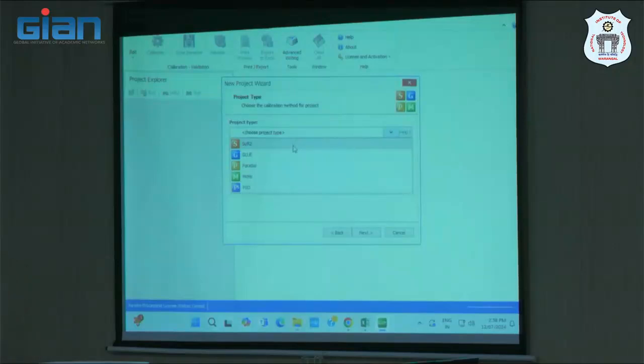Here these are the different algorithms which are inbuilt in this SWAT-CUP. First one is SUFI2, GLUE, ParaSol, Monte Carlo, PSO, particle swarm optimization. From the literature review, it is observed that when you are looking for streamflow or sediment yield, the SUFI2 algorithm is giving the best results. So that's why we are choosing SUFI2. Select SUFI2, sequential uncertainty fitting algorithm.